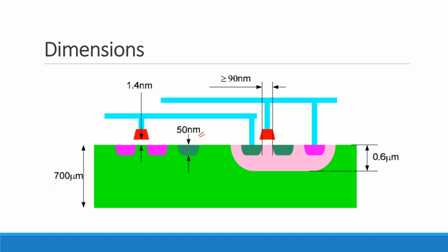The other thing that's kind of interesting here, and I annotated this, if you look at a typical silicon chip, at least while it was on the original wafer, you've probably got a thickness of about 700 microns, maybe a millimeter or so. So notice, even though I could define these super thin features, like even this gate oxide of 1.4 nanometers, I've still got this pretty thick silicon wafer. Any idea why I would make it so darn thick?